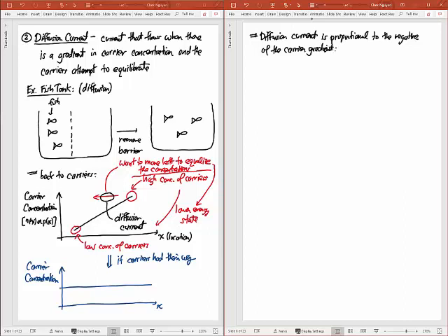Okay, so if I wanted to write expressions for diffusion current, then for example for hole diffusion, I would write J sub P, now diffusion, so I put diff there instead of drift. Okay, that's going to be equal to the type of charge I have, which is positive charge, times what I'll call a diffusivity, d sub P, times the negative of my concentration gradient.